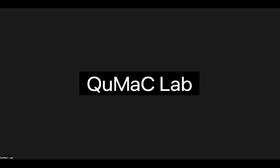So when you buy the mixer, it will tell you which sideband it rejects, whether it's the upper sideband or the lower sideband rejection as well. And all of these work in the reverse direction as well, in the sense that the IQ mixer can also be used in down conversion mode. Here I have been only talking about up conversion, right? Because I and Q are the inputs, LO is the input, and we are looking at the output.